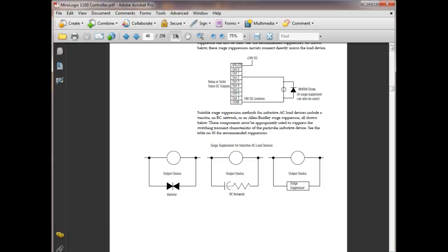So these relay coils, or these solenoids, when they come into DC, depend on a lot of wire because the only resistance that coil has is what determines the resistance of a conductor? The thickness. And what? The length. The length, yeah. And the temperature. The temperature goes up, resistance of wire. We got a temperature device called an RTD, which is a resistive temperature device that deals with the resistance of the wire changing with what? Temperature. So if you're going to put 24 volts DC across a coil, and you want it to pull 100 milliamps, you're going to have to use a lot of wire.